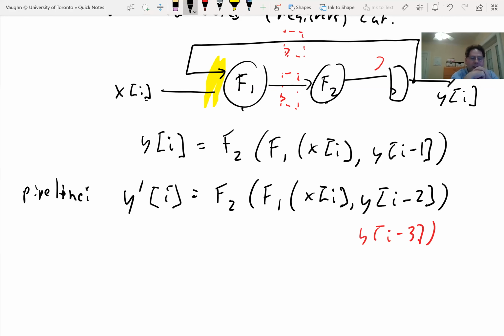Let's see, so Enrique is saying you can add a register pipeline between every register result. So you can add a register after f1 because it's already calculated. You can pipeline the feedback. You also pipeline the x of i. There is actually no way to pipeline this, basically. So you cannot change the latency of a loop. So that's your second constraint for pipelining. So you can't change the latency of a loop, which basically means you can't pipeline it.